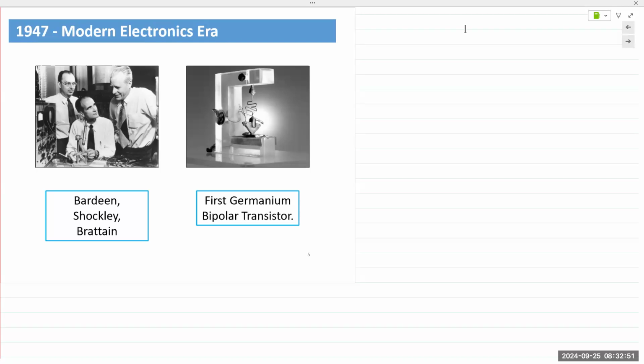So we have a class 1000 facility here. When I was a grad student, we had a class 100 and a 1000. At UCSB also, they have class 100 and class 1000. So depending on the classification, sometimes your devices would end up working well just because of how much contamination occurs in the process.